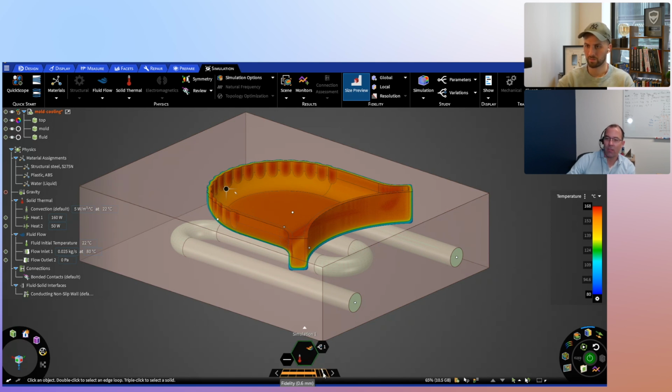If I wanted to dig further, and for those who are analysts, myself included, who want to really understand what the boundary layer is, how we are discretizing it, whether we are converging, what my Y plus is, all of those parameters that give me confidence that the answer is right, all I have to do is slide over to refine. This is the third and final mode, which I'm not going to dig into today. I'm going to focus on the explore mode because it's fast. Refine is going to give me the level of control that I might want over mesh sizing and mesh quality, and I can dig in and start to extract it out.